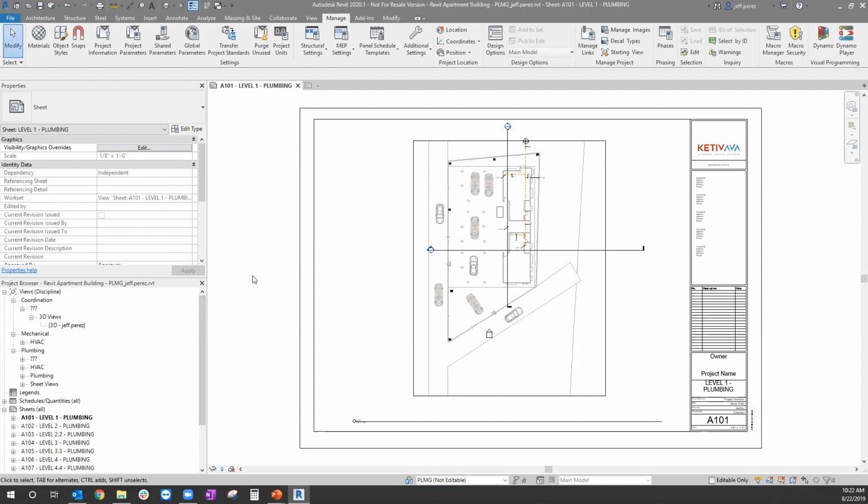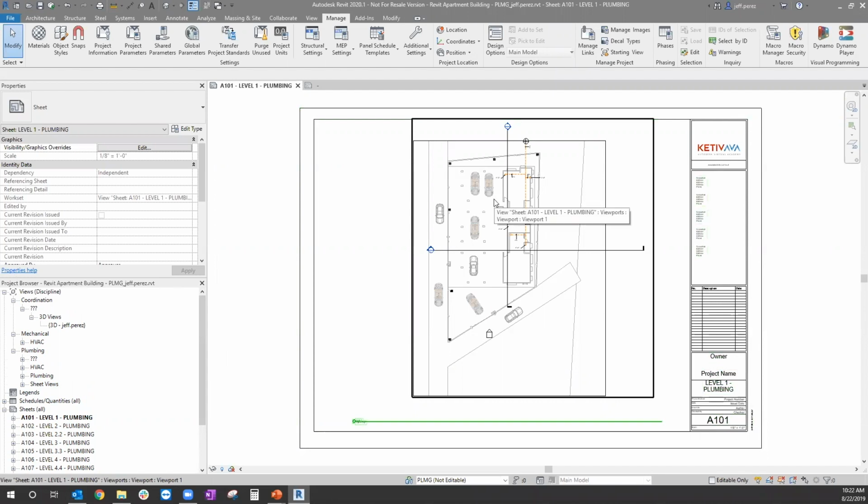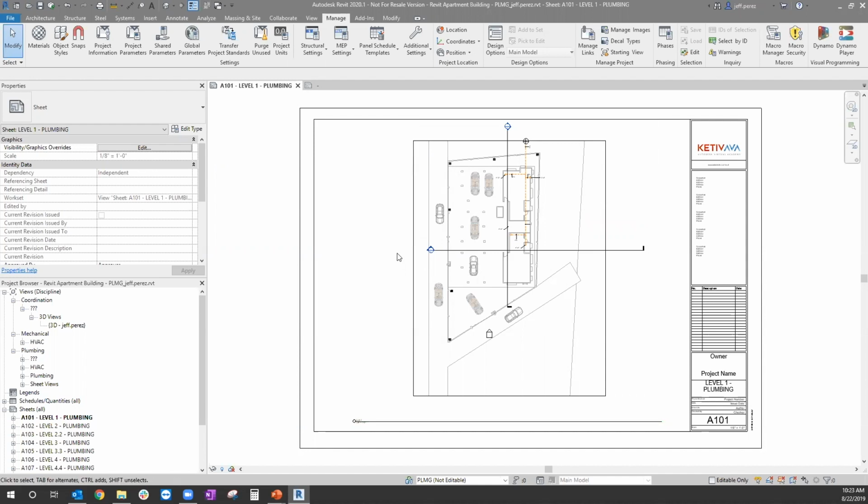So now this central model is good. It is matching, and I did get an updated link. So maybe you're going through different phasing of the project, maybe a DD phase or a CD phase. Maybe the project's not into a BIM 360 platform yet, where you're working in a live environment and it requires you to upload models constantly and downloading models. You do have to download them and then constantly clean them up and relink them. Make sure that you do have all the information in there.